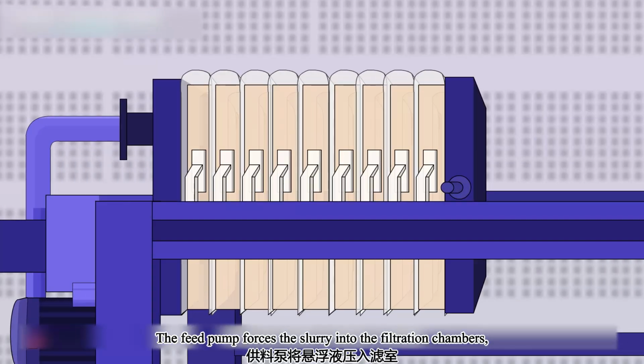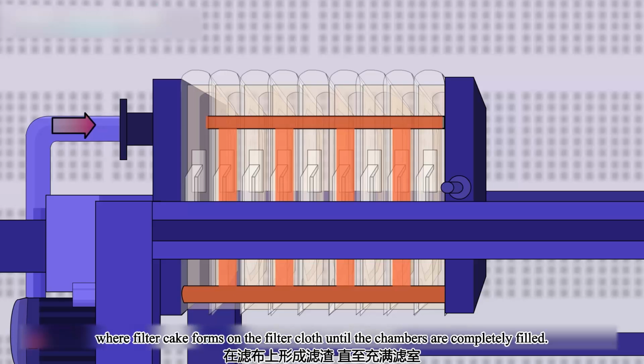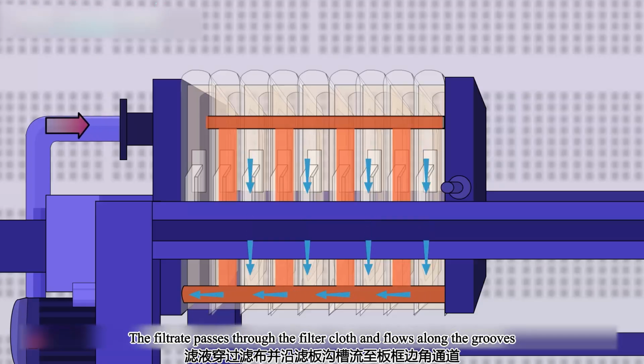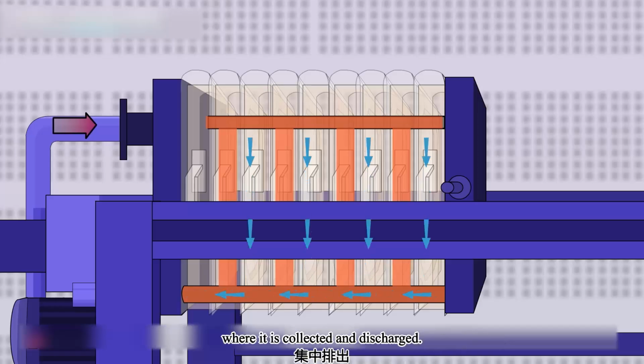The feed pump forces the slurry into the filtration chambers, where filter cake forms on the filter cloth until the chambers are completely filled. The filtrate passes through the filter cloth and flows along the grooves of the filter plates to the corner channels of the plates and frames, where it is collected and discharged.